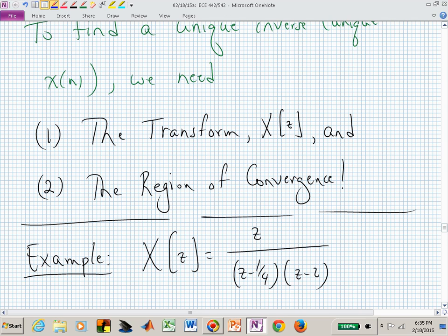What kind of a waveform is it? Causal or non-causal? And if you don't remember, just go back to the definition and look at a convenient value for z. This will be causal, non-causal. Non-causal. Do you see the other pattern that we could inject here? We could say, a region of convergence beyond both poles. Then it would be one-sided causal.